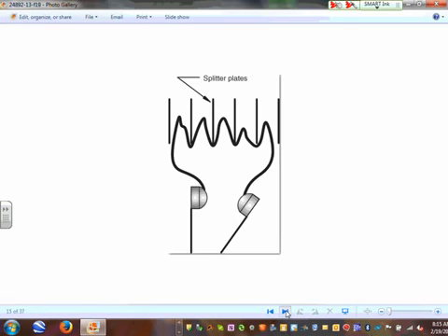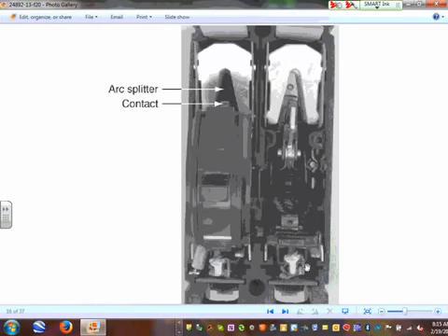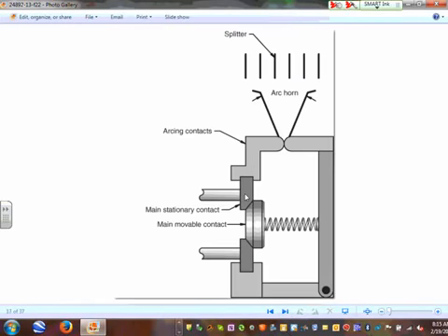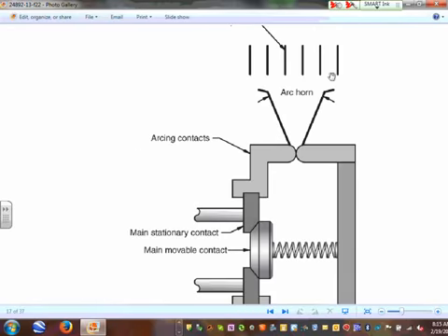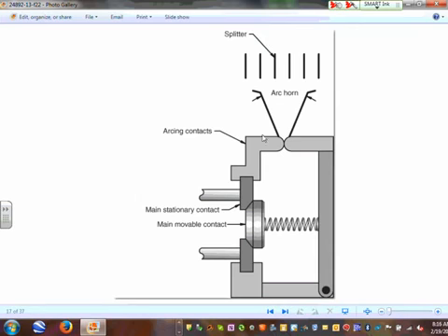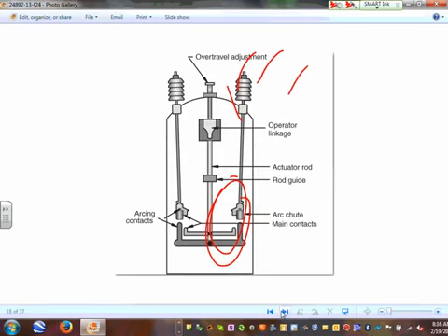We talked about the arc, extinguishing the arc, the splitters. Here are the arc contacts and the arc splitters; they remove the arc away from the main contacts. Here's another way, horns, Adam, where you channel the arc away from the contacts. So you can go to the splitter and split the arc, extending it. It cools down. It helps opening the contacts. Here's what happens when the circuit breaker interrupts, guys. The arc is drawn away, and instead of arcing here, it arcs right here. So you move it away from the main contacts. So who cares? Your contacts will live longer.